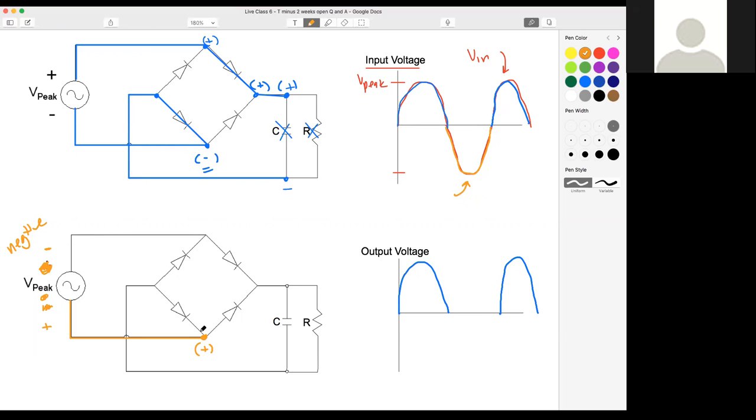Which diode is going to be forward biased? The right. Great job, Daniel. Omar, yep. Kahina, Bernie, absolutely. Benny, excuse me. So great. This one's acts as the short circuit. We get to right here, right? We still have a positive. Again, we're going to ignore our capacitor and our resistor for now. And then we're going to come all the way back to here.